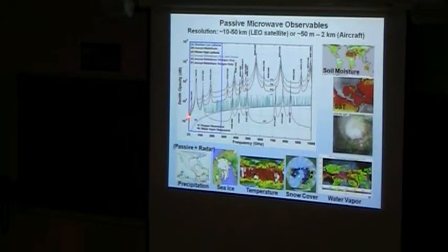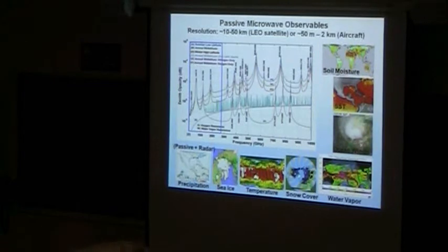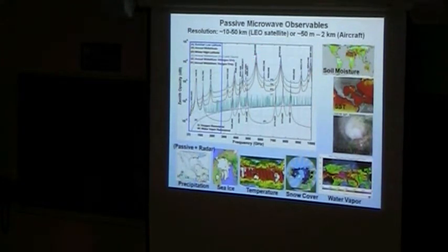And this is a rather interesting region because it goes from virtually completely transparent. This is an opacity of basically less than 1/10 of a dB. That's pretty transparent. All the way up to places where the atmosphere is very opaque, 10 to the 5th decibels. 10 to the 5th decibels, mind you. We know what a decibel is. Of course, 10 decibels means a factor of 10 loss in power. So you can imagine what 10 to the 5th decibels is. You basically can propagate a wave on the order of a millimeter or so before you start losing its energy.